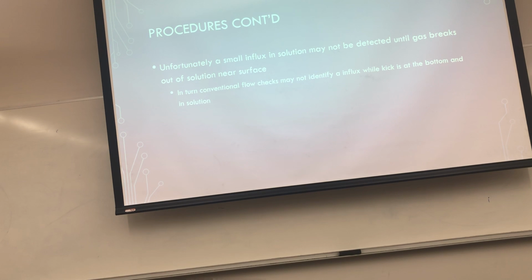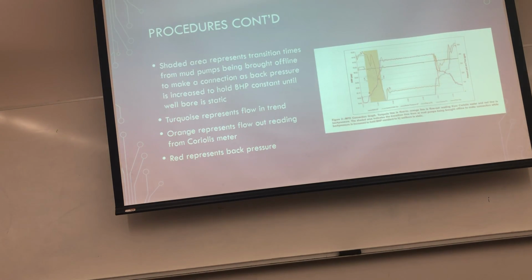Unfortunately, a small influx in solution may not be detected until gas breaks out of solution near the surface. So in turn, conventional flow checks may not identify an influx while the kick is at the bottom and in solution, which could pose some serious danger.